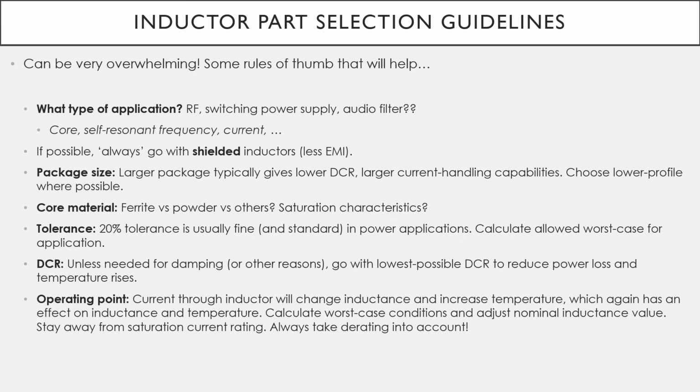In general, if possible, it's mostly advisable to go with shielded inductors rather than unshielded because they have typically better EMI performance. Package sizes, as you go larger in package sizes, typically this will give you lower DCR. Depends, of course, on your inductance values and more, but also larger packages might allow you to have larger current handling capabilities. They might give better temperature performances and more. I'd also suggest choosing lower profile packages where possible, also for EMI reasons.